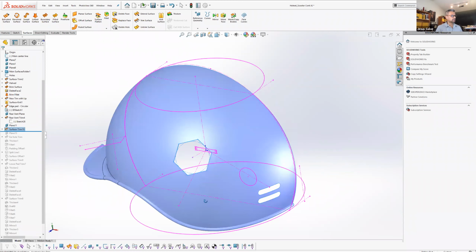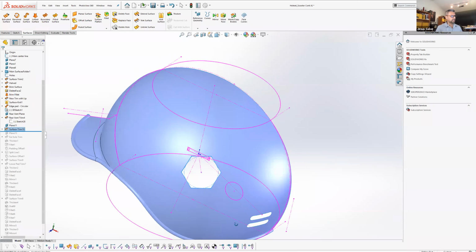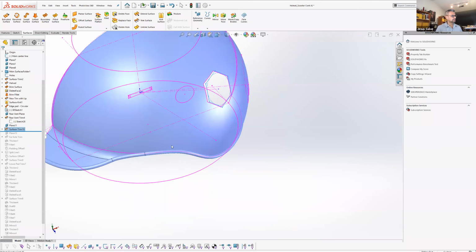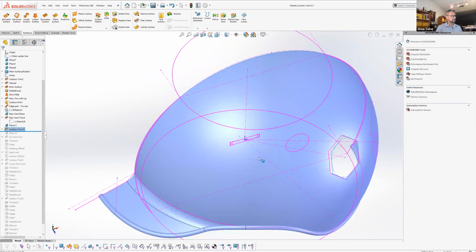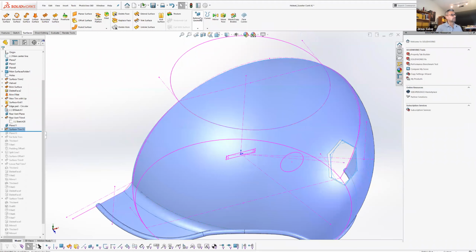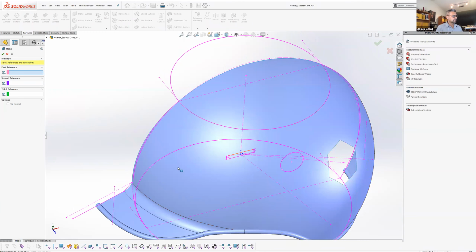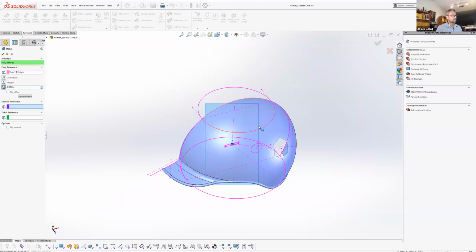And as always, you can also just rotate your model to the location of where you want that design or whatever it may be. Go to your reference plane, start a new one, select any vertex. In this case, I'll do that. And then select create a plane parallel to the screen. So now there's a plane parallel to where I'm looking at.